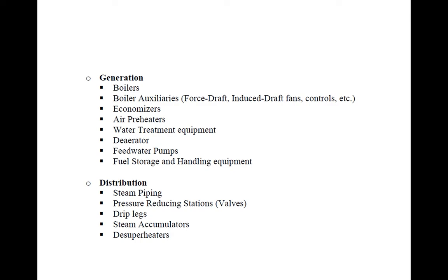because when the oxygen reacts with the ferrous, which builds the material of boilers. Boilers are built from iron, whose major element is ferrous. When ferrous or iron contacts or reacts with oxygen, an electrochemical process takes place, which is the corrosion process.